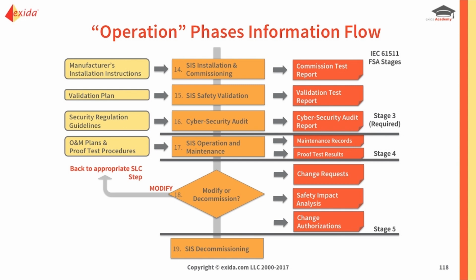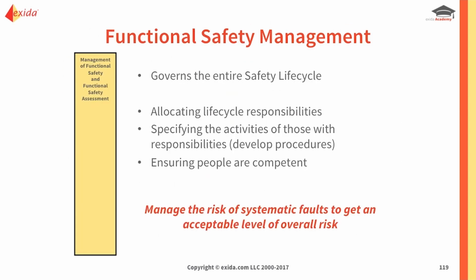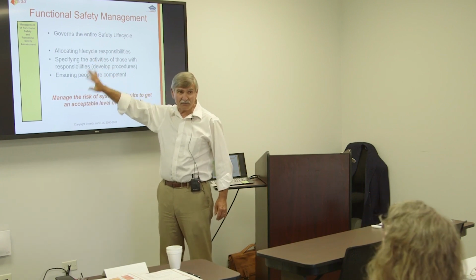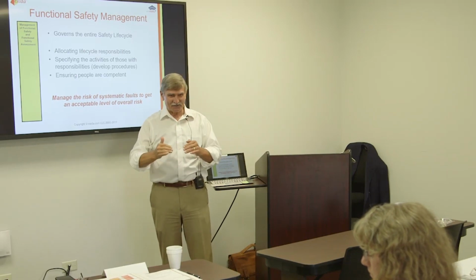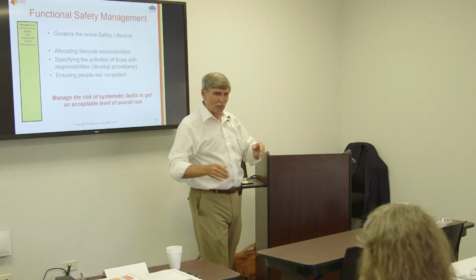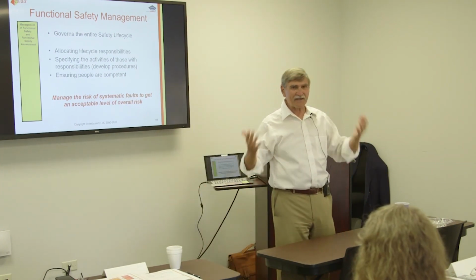That is the safety life cycle in a more detailed way with the process industry examples. There is a column on the left-hand side of that chart in 61511, and an identical column in 61508, that talks about functional safety management. Basically there are a set of requirements that states you must have a written, documented procedure. Someone must be checking to see if people are following the procedure. And there's a whole long list of stuff that popped right out of my basic quality training from 1970.